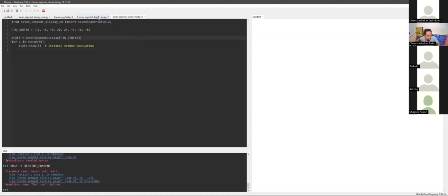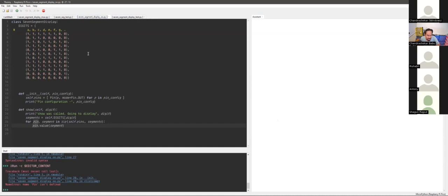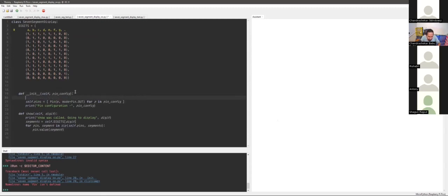Oh, pin is not defined. Oh, obviously. See here, I've created a class, so I'm using this class called Pin, right? Where does it come from? machine, right? I have to load this library here. I can put this import inside the init method also. That is what I will do, but some people say put it on top. It's up to you. Because I'm using Pin here, I can directly say from machine import Pin.